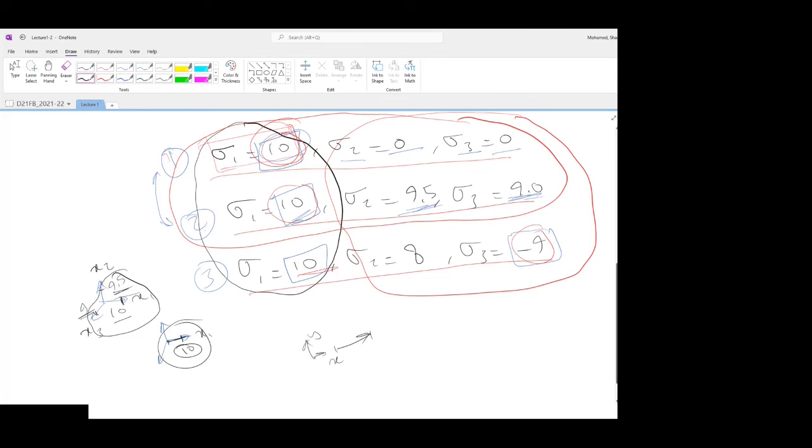Now, it's not just that. When you project your stress into principal directions, you'd be actually projecting into the normal direction of the stress. But there will also be some projection in the shear direction. Now, the shear is also quite critical for failure. And then the interaction between the normal and the shear forces, or the normal and the shear stress, would probably be very critical for failure.